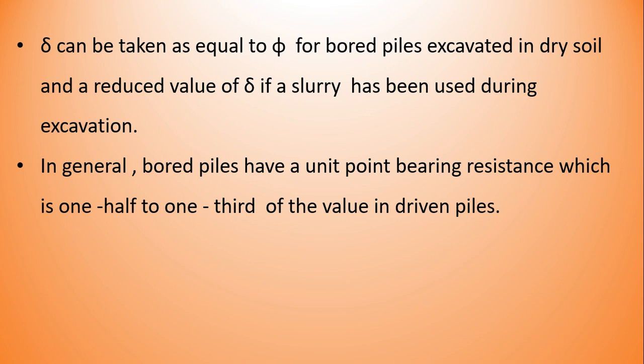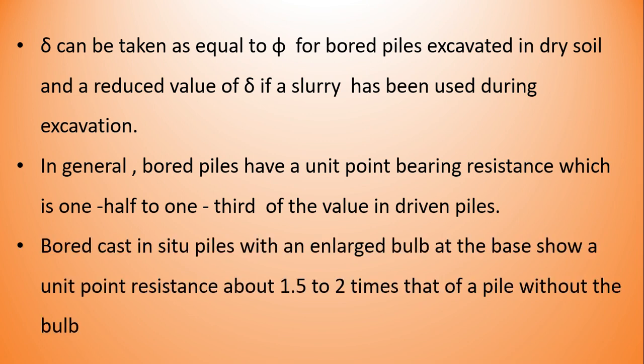In general, bored piles have a unit point bearing resistance which is 1/2 to 1/3 of the value in driven piles. Bored cast in situ piles with an enlarged bulb at the base show a unit point resistance about 1.5 to 2 times that of a pile without the bulb.